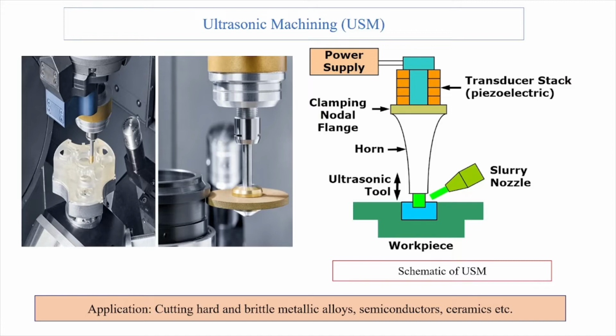Actually brittle materials are poor conductors of electricity, so those materials maybe can't be machined by ECM or EDM processes. So this method is suitable for cutting brittle materials also. The applications we can say, like cutting hard and brittle metallic alloys, semiconductors and ceramics.